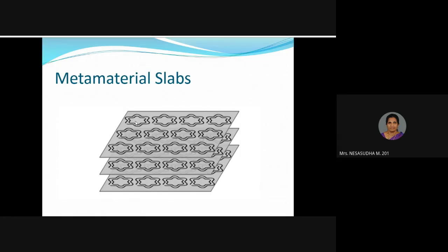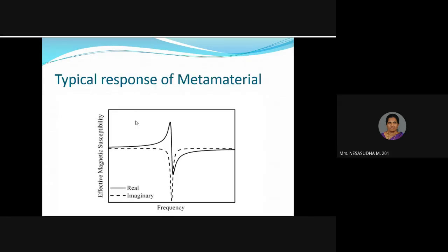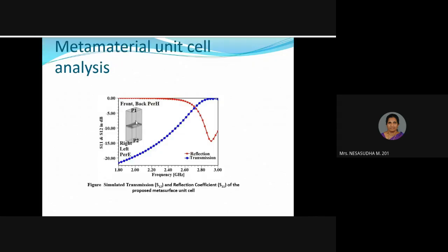When you take an antenna, we would already have learned it in the morning session also. Ma'am would have explained clearly what an antenna is and what the different layers of an antenna are. When you take the microstrip patch antenna, we can have mainly 3 layers. One is the ground layer. Over the ground layer we have the substrate. Over the substrate we have the radiating element, or antenna. First we have to design the antenna.